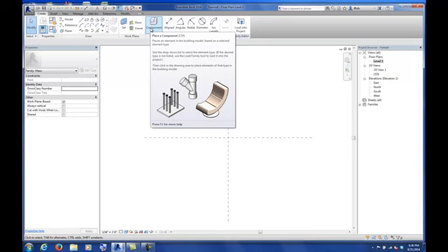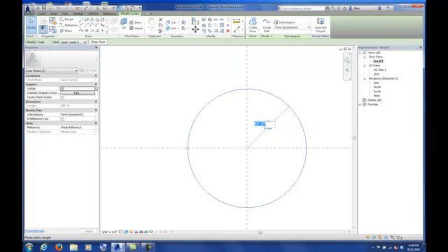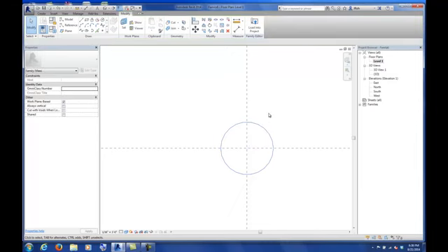And in Revit, anytime you see those pop up, you can actually click on the text. And I could type in a different dimension like 25 feet. And that's going to change my object. So the way that Revit works a lot of times is you draw first, you just kind of put something down first, and then you can edit what its size is, or if you want to be more specific, you could type in the actual dimensions as you're going.